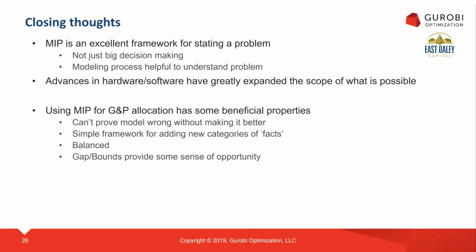And then the second to last thing that's very useful is gap and bounds. We just as easily could have written an algorithm or a heuristic to partition the wells between the systems. The problem with heuristics and algorithms is you really don't have a sense of how close to being optimal they are. One of the features I really like about optimization is that, because of the mathematical qualities they've proven with linear programming, we can find a bound. We can look at our current incumbent solution and calculate a gap, so I know that nobody's algorithm with the same exact weighting and data can do better than, say, 2% better than this.